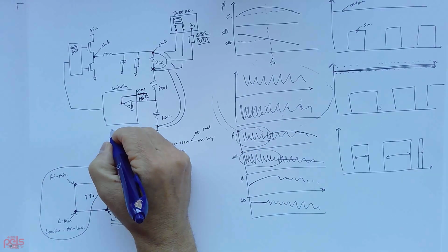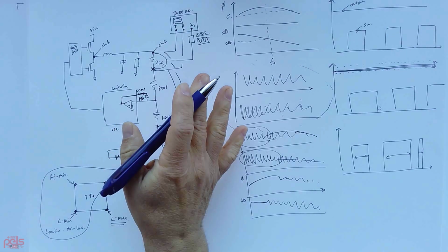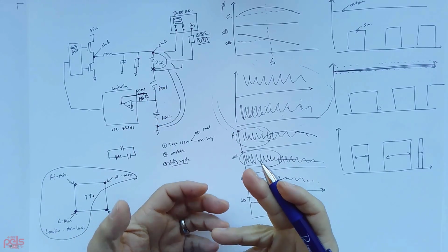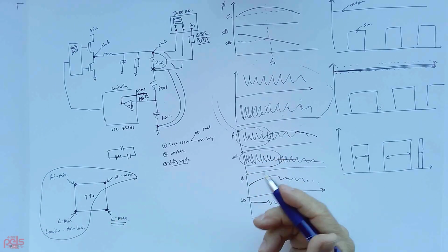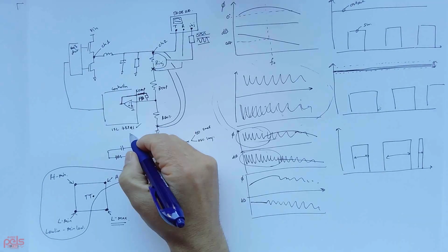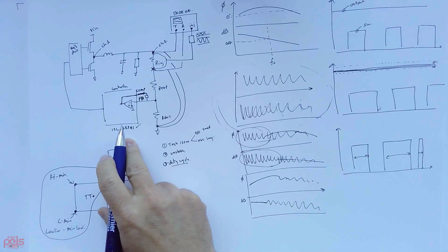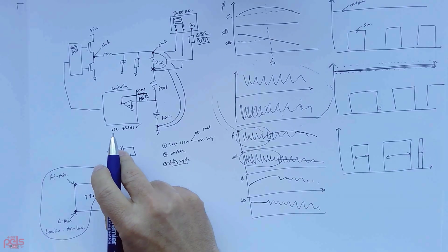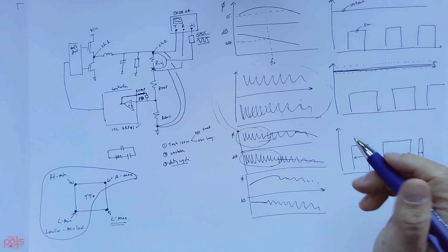So in my case, I was working with an ISL78841, which is a very simple controller. The reason I was using that is because the applications that I work with are space applications, and I needed a radiation hardened device. And this is typically the go-to device that I work with. In this case, the duty cycle is limited to 50%, and the COMP pin has a limit of 5 volts. It can go between 0 and 5 volts.